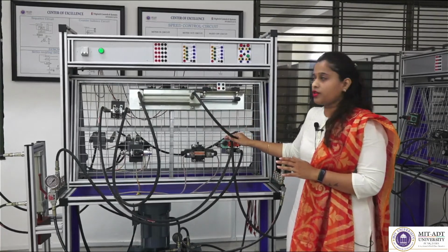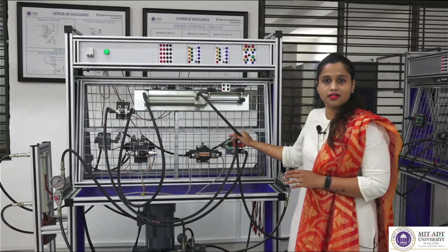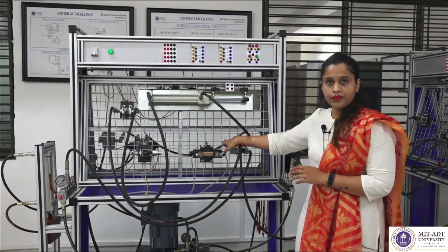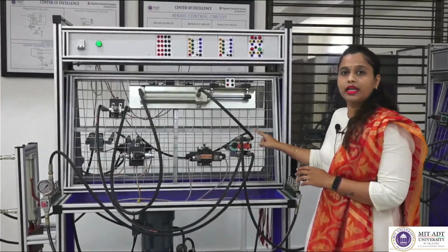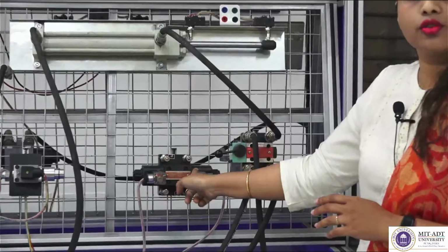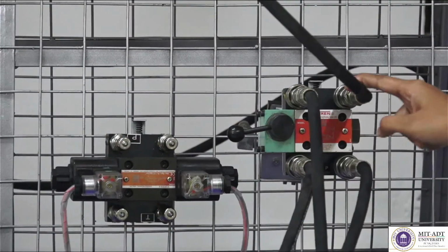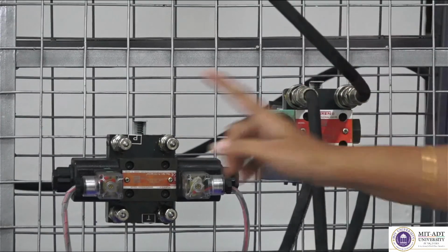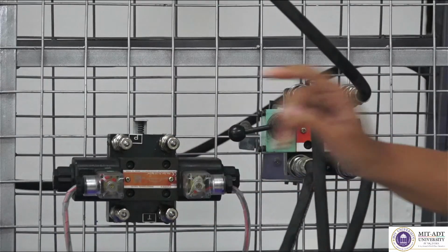This circuit which I have told you about was the basic hydraulic system which has been driven or run with the help of some manual control. Now, let us switch the DCV from this 4x3 lever operated spring loaded DCV to a both sides solenoid operated 4x3 DCV. So, what I am doing? I am exchanging all those 4 connections and putting them over here to this solenoid operated DCV. Just give me a second.